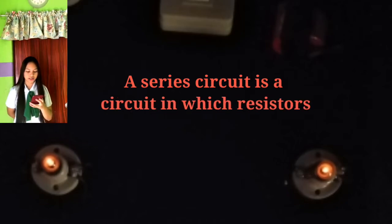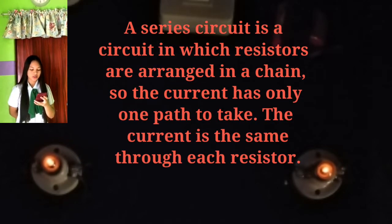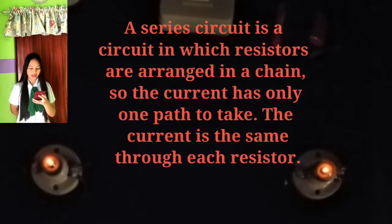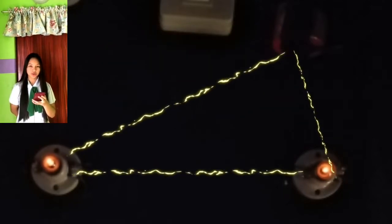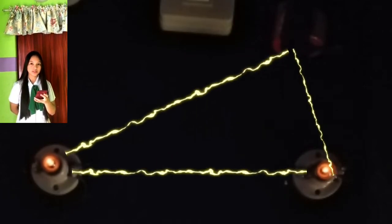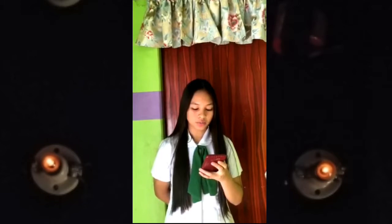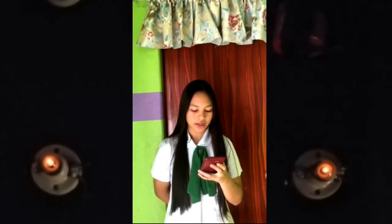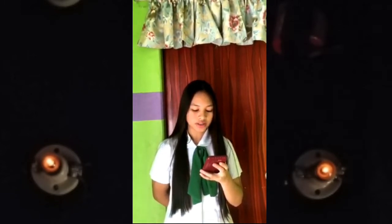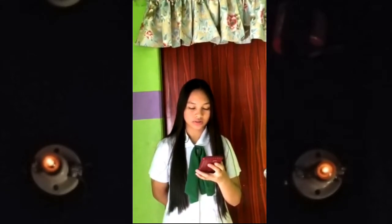A series circuit is a circuit in which resistors are arranged in a chain, so there is only one path to take. The current is the same through each resistor. The total resistance of a circuit is found by simply adding up the resistance values of the individual resistors. In a series circuit, the current that flows through each of the components is the same, and the voltage across the circuit is the sum of the individual voltage drops across each component.